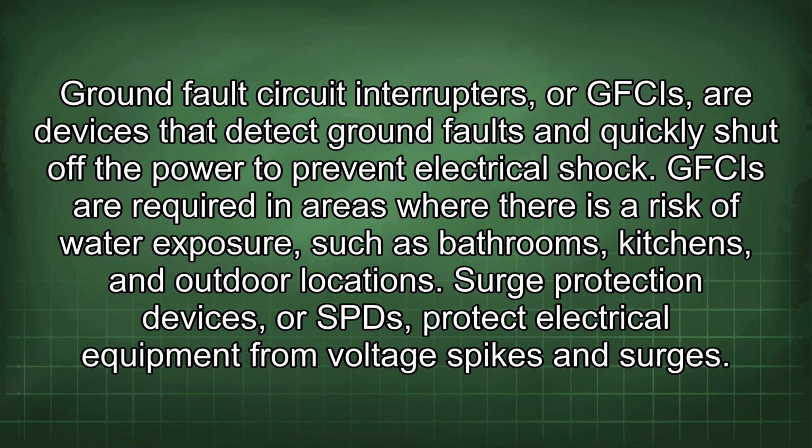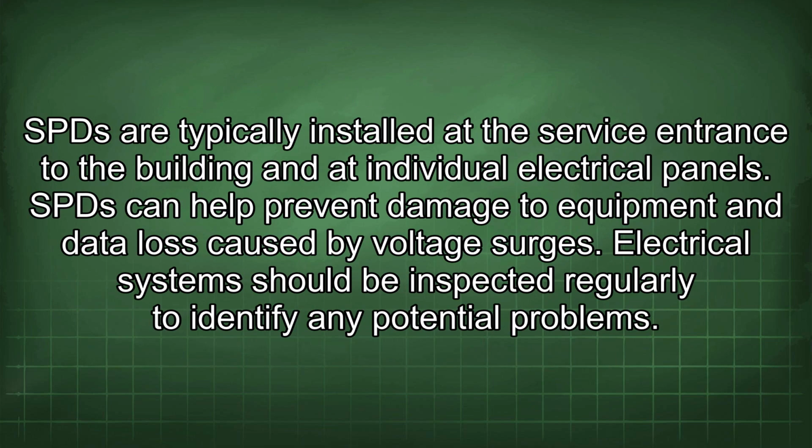Surge protection devices, or SPDs, protect electrical equipment from voltage spikes and surges. SPDs are typically installed at the service entrance to the building and at individual electrical panels. SPDs can help prevent damage to equipment and data loss caused by voltage surges.